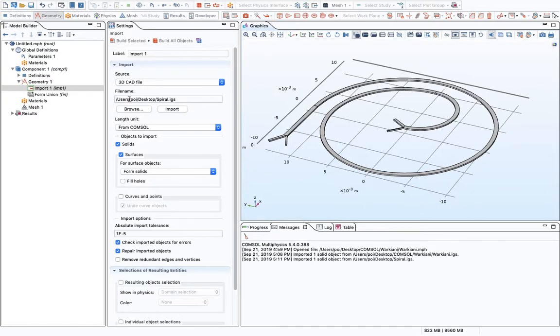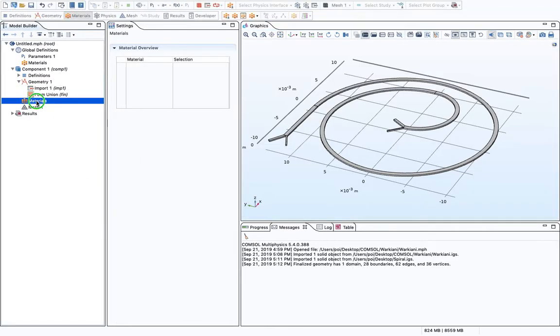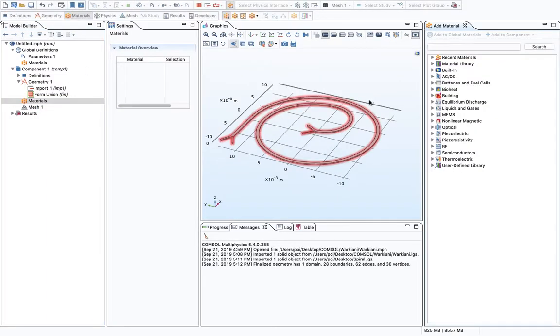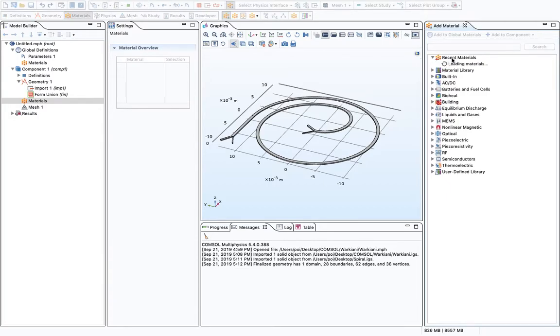actually add in the material that I want, which in our case is liquid water. So I just go ahead and right click on the material here. You can of course use this panel up in the upper part of the window as well. I right click on the material and add material from library. I can use liquid water from the liquids and gases part, and because I've recently used water, I can go ahead into recent materials and choose liquid water.